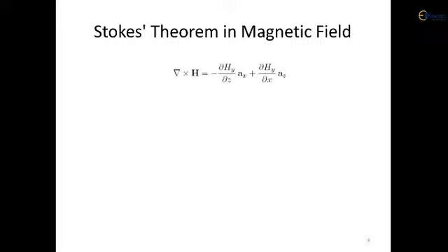So in this expression we have to put the Hy component. Hy component, we have just seen, is x plus 2y divided by z square, which we substitute here. After finding the differentiation with respect to z and x, it is equal to 2 in the bracket x plus 2y divided by z cube, further multiplied by ax, and this is further added by 1 upon z square az in terms of amperes per meter here. So this can be the solution for part A.